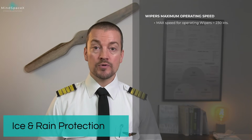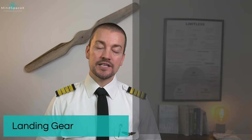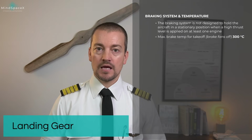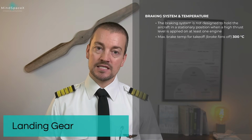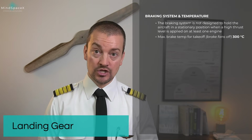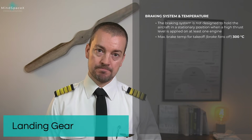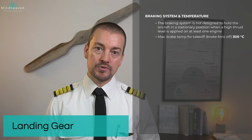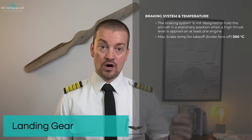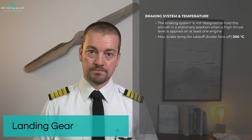Maximum speed for the window wipers we've already covered. That was 230 knots. The landing gear also has limitations, although we have covered some of them already. Here's one we haven't covered. The braking system, first and foremost, is not designed to hold the aircraft in a stationary position with high thrust applied to at least one engine. Maximum brake temperature for takeoff is 300 degrees Celsius, brake fans off, and 150 degrees Celsius with the fans on.